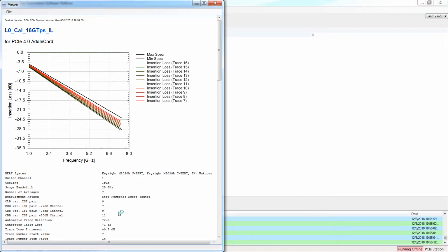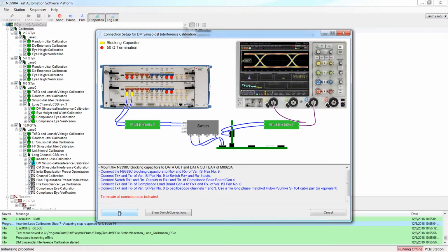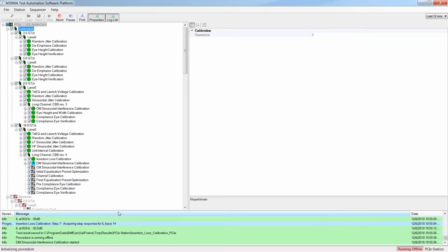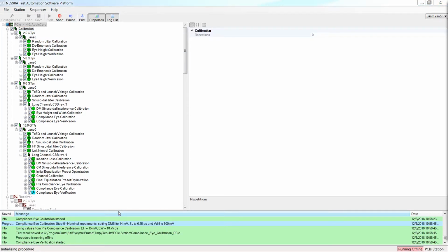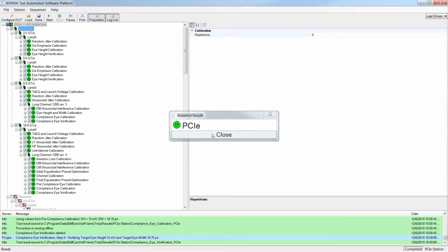This report contains the results of the chosen test procedure, including the specific test parameters. Also in the output console at the bottom of BitifEye, we can see the progress information log for each test step. A green smiley will indicate that all the calibrations were finished successfully.